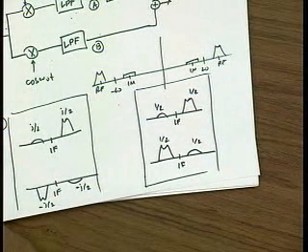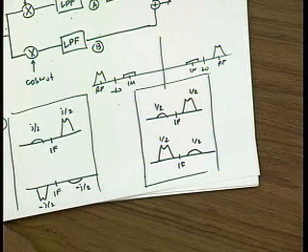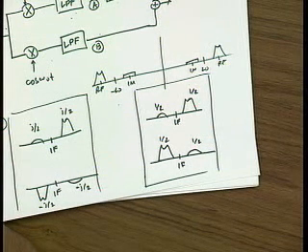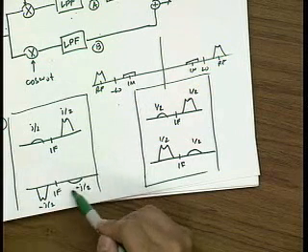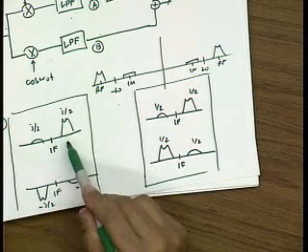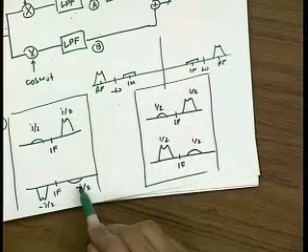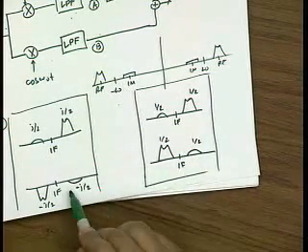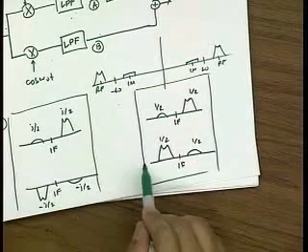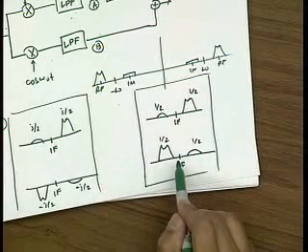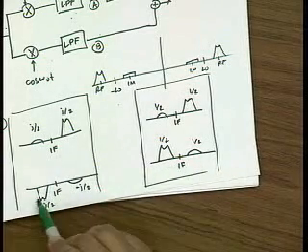All right? Now we begin to see how we might possibly perform image rejection. Okay? So right now, this is the image term written on top here that we'd like to get rid of. You can see here the image term is actually out of phase. So if I sum these two signals together, this image term would cancel out, but then so would the signal term, right?